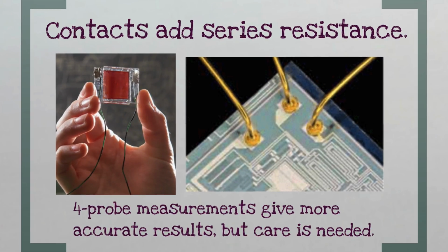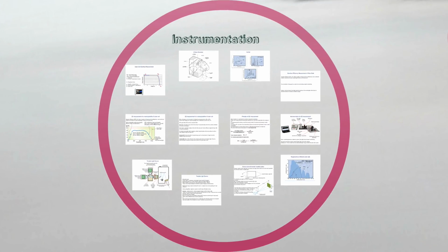The other thing, as I mentioned before, is the series resistance and contact resistance. In other words, when you try to measure a cell, of course you have to contact it, and there's always some contact resistance, not perfect. That always shows up as some deformity in your IV curve, and you have to be careful about this. You can do 4 probe measurements, which, as you electrical engineers know, is basically a differential measurement. Not so important, but it's possible to do. You can get very precise results with slightly better equipment. So just be aware of it. Those are on the measurement side for solar cells.